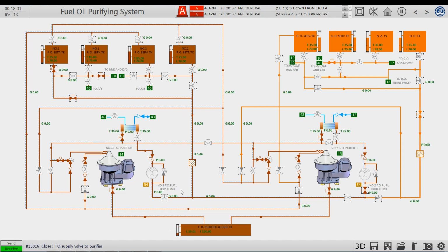The inlet valve for the oil pump should be opened. The inlet valve of the heater should be opened. Open the valve of the separator net oil outlet. Open the oil inlet valve of number 1 heavy oil service tank. Open the oil return valve of bypass line and the oil inlet valve of number 1 settling tank. Make sure other valves leading to suction and outlet are closed.